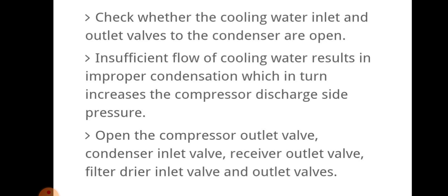And check whether the cooling water inlet and outlet valves of the condenser are open. Insufficient flow of cooling water will result in improper condensation, which in turn increases compressor discharge pressure.